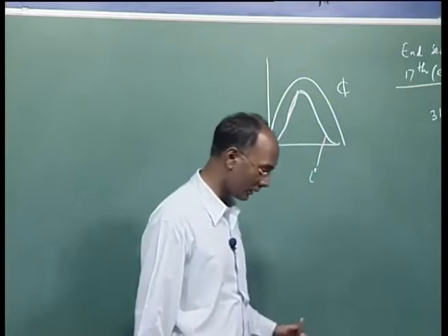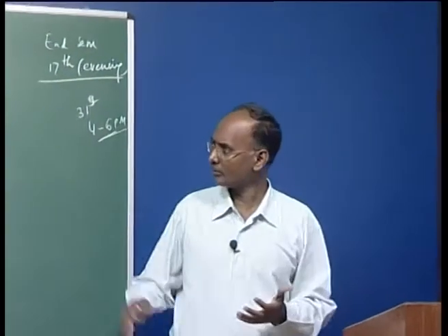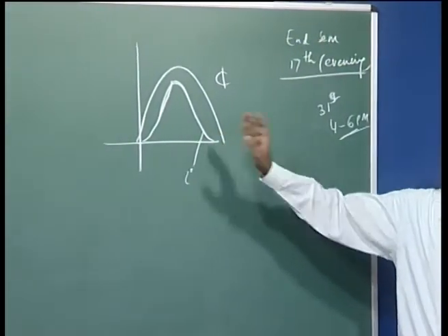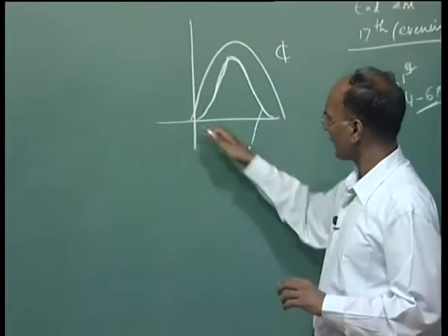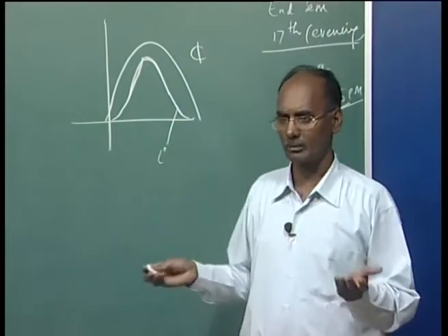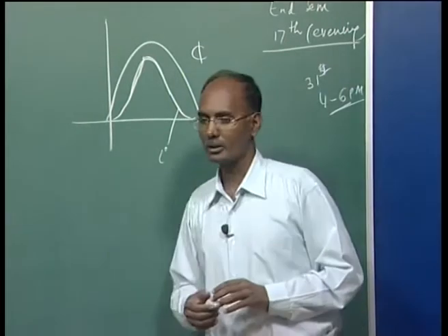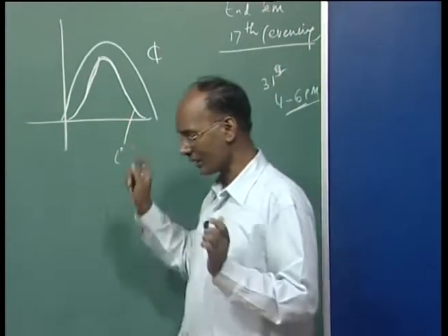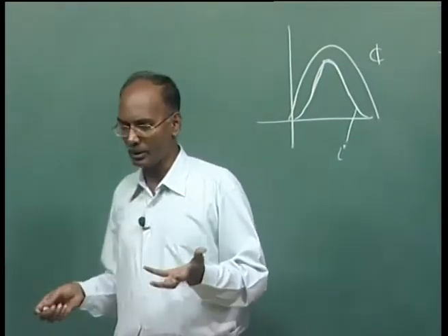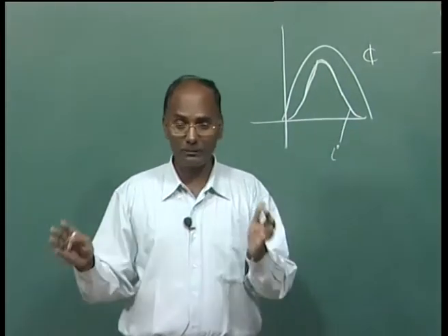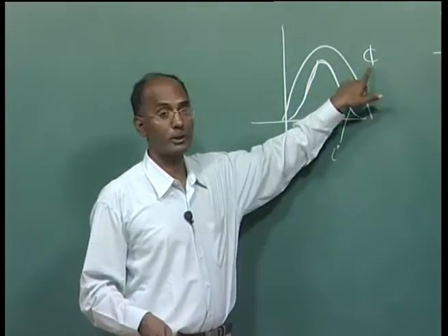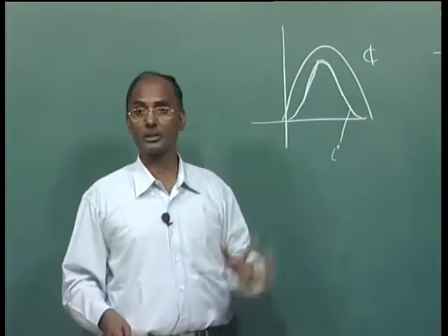But again, if you look at the components here, the magnitudes of some are very small, but some components, like the second and even the third order, are quite significant in these harmonics. But again, the magnitudes are small, so we can skip discussing them here. My concern here is the harmonics generated by the converter circuit. The harmonics generated by a normal conventional transformer are less compared to the converter transformer, because the converter transformer works at a high flux density. So, more flux, more distortion, more harmonics.